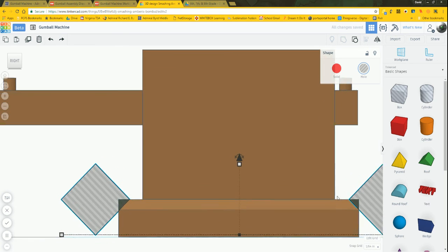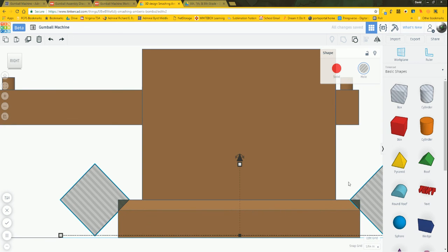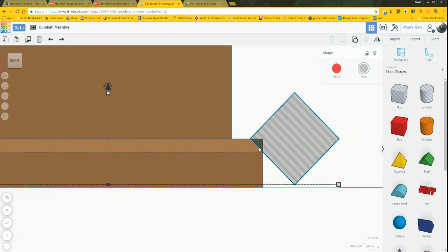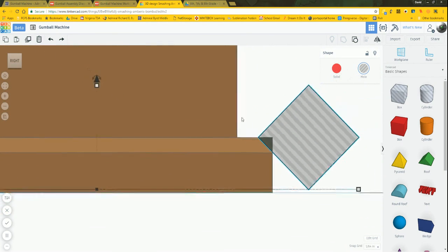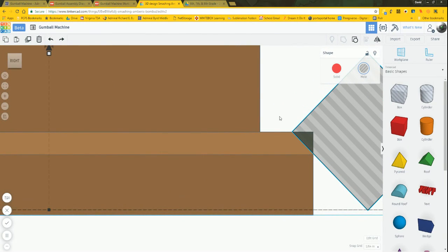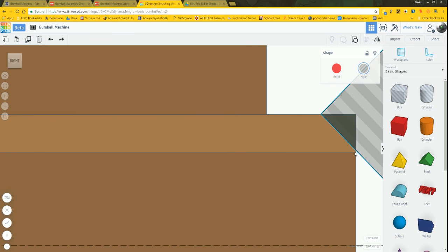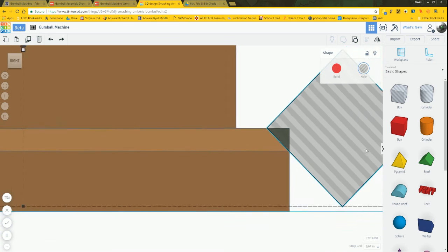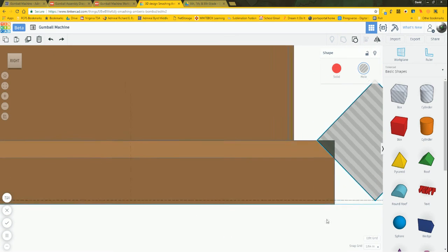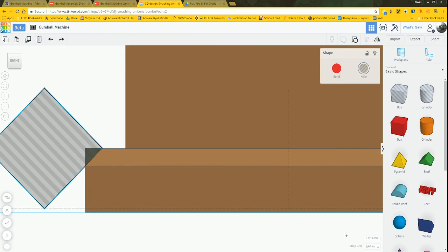Now, because I already chamfered one part, I should be able to just check and make sure I'm cutting through this bottom corner, because we want the chamfers to be all the same distance. So as long as that goes through here and it comes through that top, we're just fine. Now you could potentially, same thing over here, we're good.